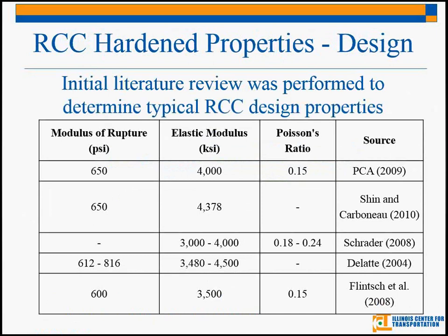A lot of work has been done on the properties of RCC. I'm going to go through some of our literature review right here. What we found, and what a lot of people have found, is that RCC has a lot of similar properties to conventional concrete. In terms of modulus of rupture, 650 psi is a very typical design value for conventional concrete, and the elastic modulus and Poisson's ratio are very similar to our conventional paving concrete.